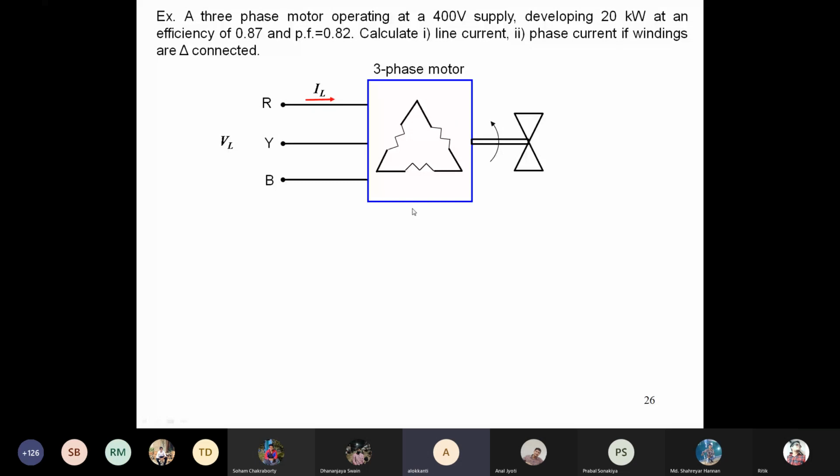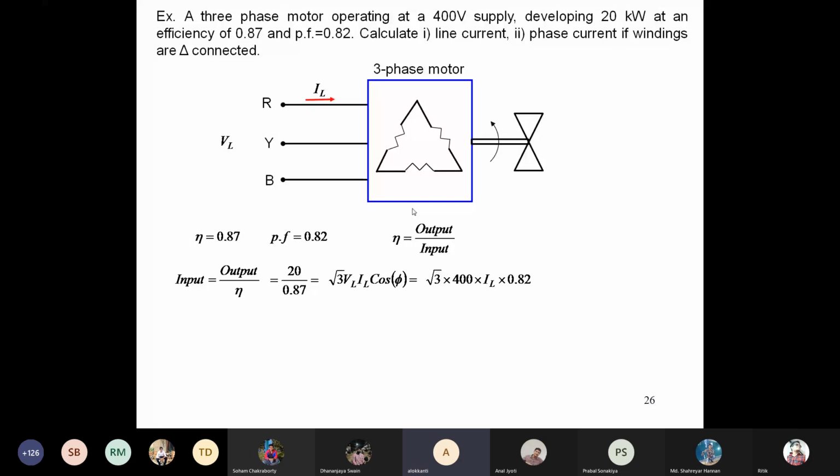Answer. Okay, then I have to show everything. Okay, the derivation is there. And again another thing is this is 3-phase, so this is the formula root 3 VL IL cos phi. How will we know whether it's leading or lagging? It is a motor. Motor is full of windings. It is only lagging. Yes, sir. Inductor. It is not told here, but it is okay. So these are the answers.